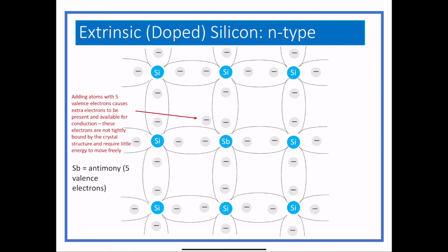And it is easier for this electron to gain enough energy to go off into the conduction energy level than it would be for one that is bound. So they tend to float off really easily, easier than the electrons that are in the original structure. And they don't leave a hole behind. And that's the key. There's an electron available, it becomes available for conduction of electricity, but doesn't create another hole in the process. So that is what you do when you get N-type material.